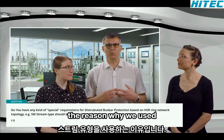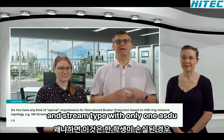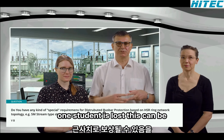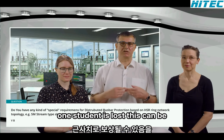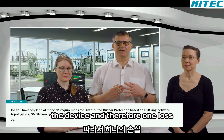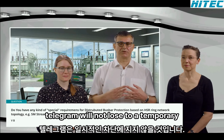That's the reason why we used a stream type with only 1 ASDU, because if one stream is lost, this can be compensated by a linear approximation in the device, and therefore one lost telegram will not lead to a temporary blocking.